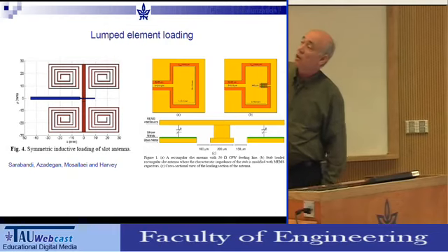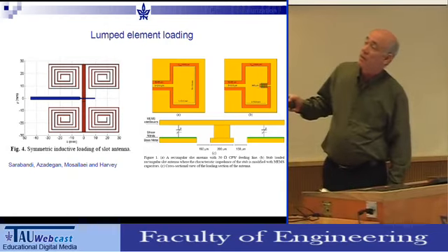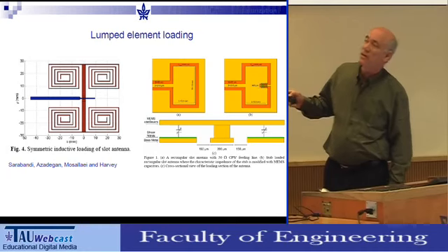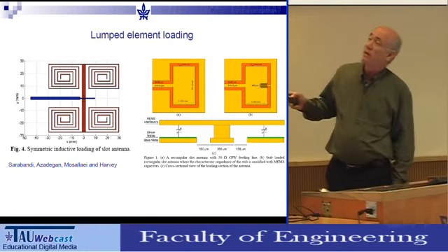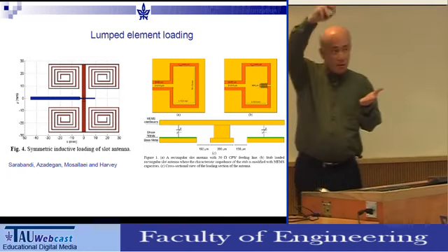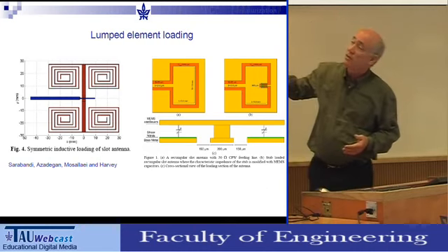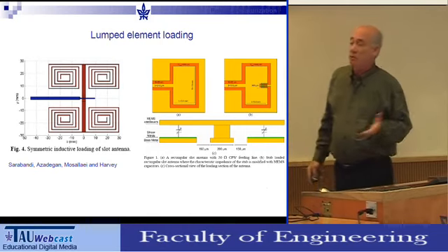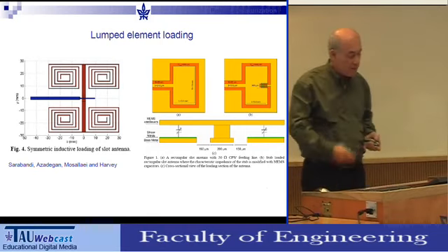This is also a slot, as you can see here. This is the microstrip line that feeds the slot, and this is the transformer and the stub to match the feeding point. But then the slot curves around, it meanders around and around. You could call this an inductor, if you like. So you were able to reduce the length of the slot simply by letting the field go around and around like so. By how much? You know the answer.